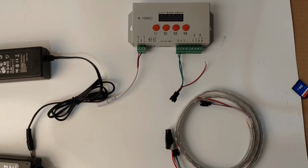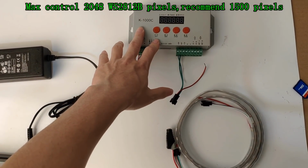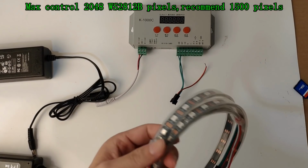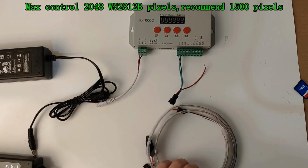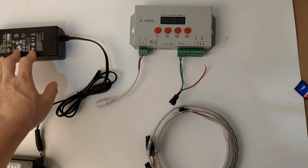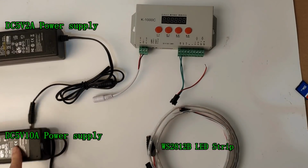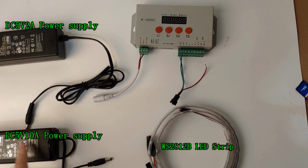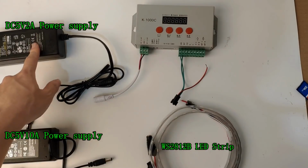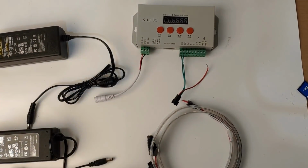Hello, I'm going to show you how to connect the K-1000C controller and this WS2812B LED strip. I also use two power supplies for the controller and the LED strip. This is the DC 5 volt 10 amp supply for this LED strip, and this is the DC 5 volt supply for the controller. Let's check.